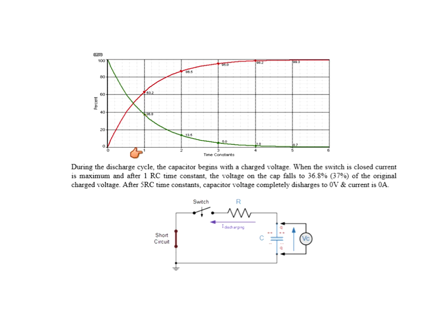The first time constant and the fifth time constant. Don't worry about 2, 3, and 4. If you know the first and the fifth, you're going to be okay. Now here's some interesting aspects about the first and the fifth time constant. During the first time constant, when it's charging or discharging, there's a lot of current flowing in that circuit.